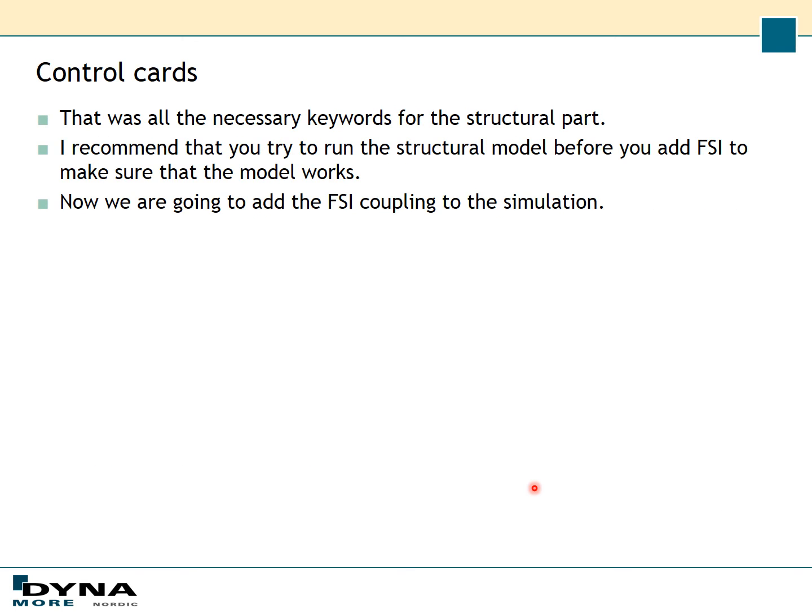That was all the necessary keywords for the structural part. So save the model and try to run the solid model before you add the FSI part. It is a good recommendation that you always try to run the structural part and the CFD part separately before you try to connect them.